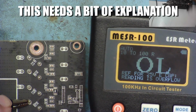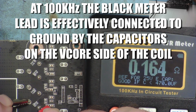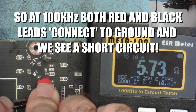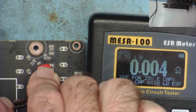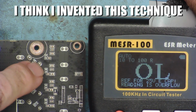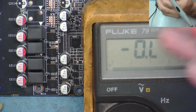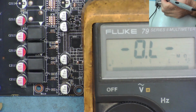Did you see it? So I'm measuring across the coil, yeah, and when I come to the one with the short, I'll see the lowest. So 0.164, 0.15, 0.13, yeah, 0.12, 0.003. So that is also showing me that this is the one that has the short on it. So we have two methods, one using the short circuit finder, one using the ESR meter, that both point to this chip being the one that has the short circuit.